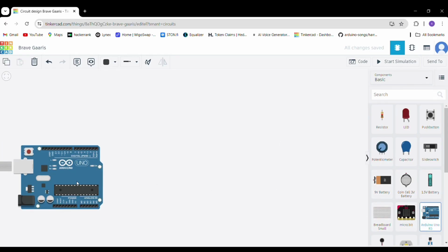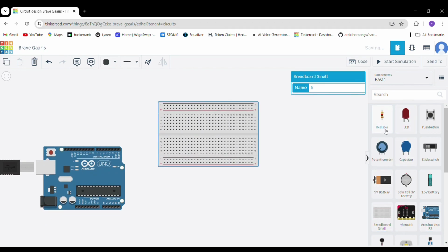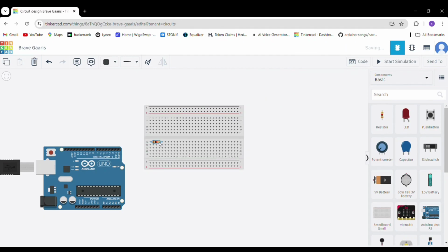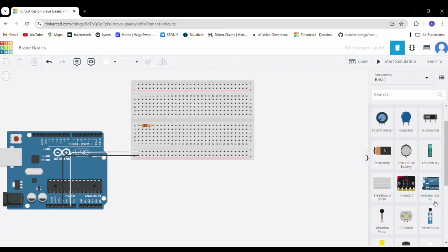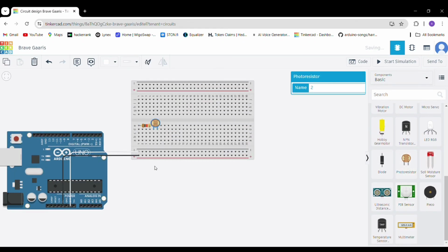We can start by making the prototype of our circuit first. For this project, you need a normal resistor, an LDR resistor, and some LEDs for the light detection circuit. And to make a simple clock, we need a stepper motor and the ULN2003 stepper motor driver. You can use the 5-volt and GND pins to make a general connection to the breadboard.